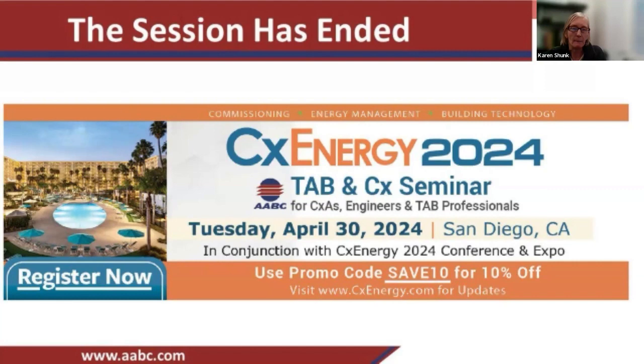Yeah, okay. Here's another one I think you could probably take care of pretty quickly. Are there good reference guides for reasonable tolerances? Yes, the AABC standards. They have great tolerance guides in there for specifying and giving you a good accountability of what you should expect relative to TAB instrumentation, like I talked about. It has its limits, but standardized, I would say plus or minus 10%. If you really wanted to do yourself a great service in a lab situation, do plus or minus 5%.